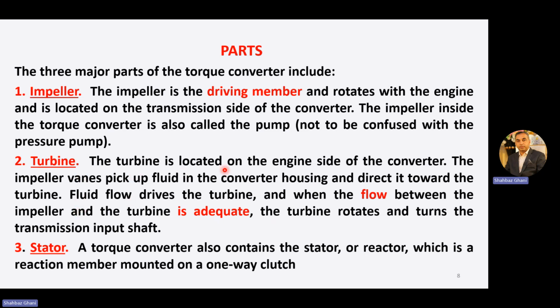The impeller vanes pick up fluid and direct it towards the turbine, and when the flow is sufficient, the turbine rotates and turns the transmission input shaft.